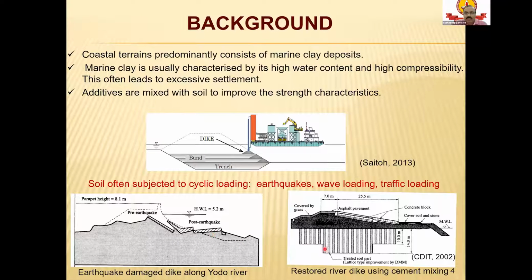After that, they did the cement treatment, I mean deep soil mixing columns, and then they created the entire thing again, and they thought that it was fine. But what happened is that in 2011, during the Fukushima earthquake, this entire pavement collapsed again, and a kind of 45-degree failure plane developed in these deep cement mix columns. So that's where we started.